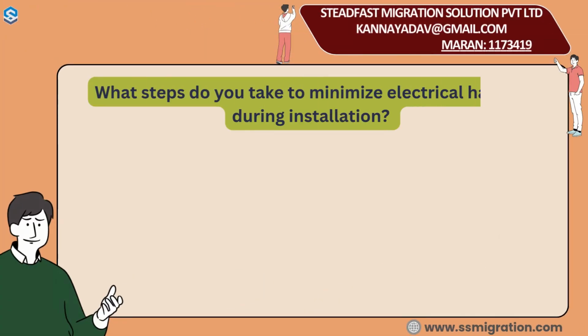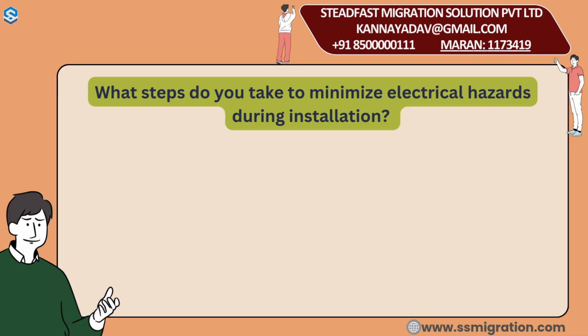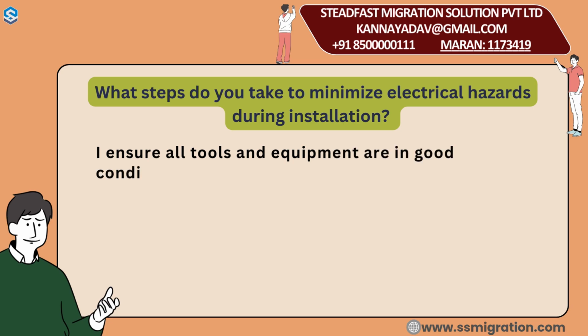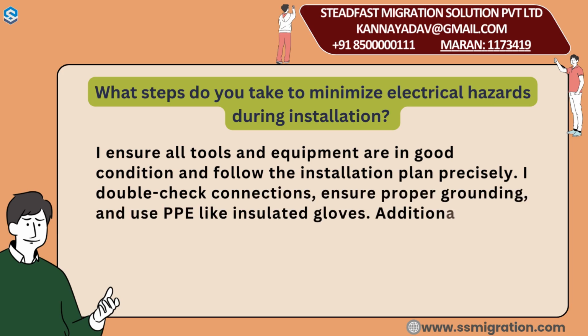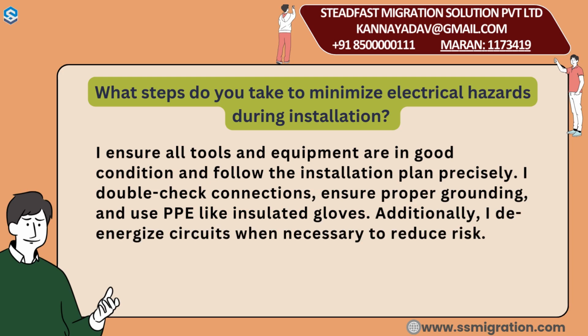What steps do you take to minimize electrical hazards during installation? I ensure all tools and equipment are in good condition and follow the installation plan precisely. I double check connections, ensure proper grounding, and use PPE like insulated gloves. Additionally, I de-energize circuits when necessary to reduce risk.